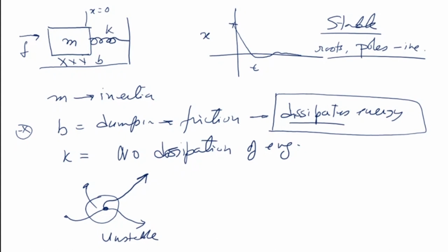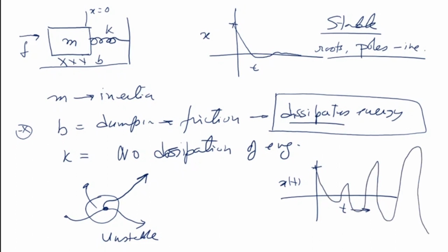In terms of the spring mass damper system, suppose this will not happen, but suppose you put M, B, K, either of them to be negative, and it becomes unstable. Then what it basically means, if I give a force, move the mass to a distance, and I leave it, then what will happen? This oscillation, instead of coming down, is going to increase. Okay, this is again an unstable system. So it is not coming back to where it started, it is going off somewhere else now. Okay, so this is an example of an unstable system now.